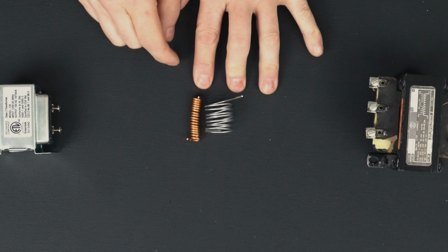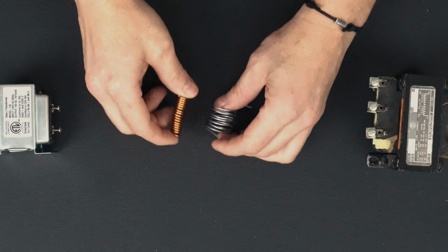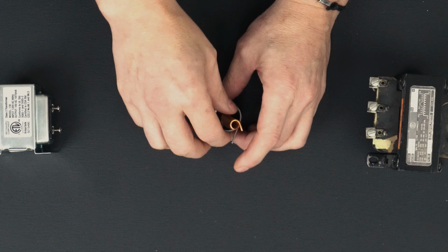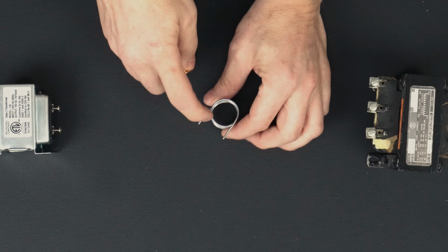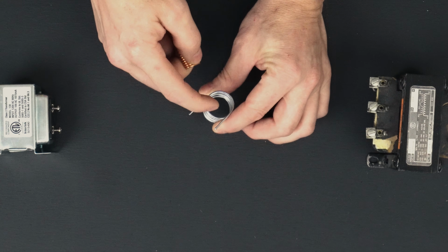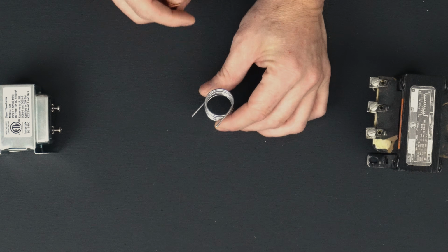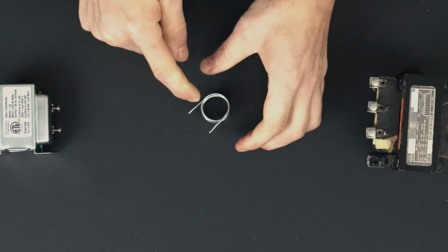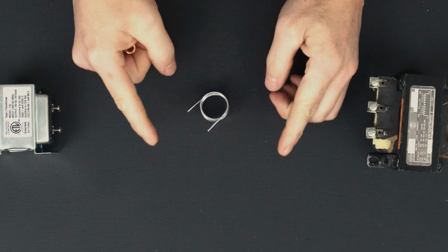There might be 3 of them, and if it's a 3-phase transformer, you'll have 3 coils side by side, but you can also have coils inside of each other. So when you put them inside of each other, when I was saying that there was an expanding and collapsing magnetic field, well, you want to capture most of that field. It goes all the way around the conductor, right? So as there are all of these lines of force around this thing, all the ones on the outside don't really do much, but the ones on the inside are focused really tightly. So we have a strong magnetic field on the inside of this because they're all collecting together in the middle, and then it's a little bit weaker on the outside.